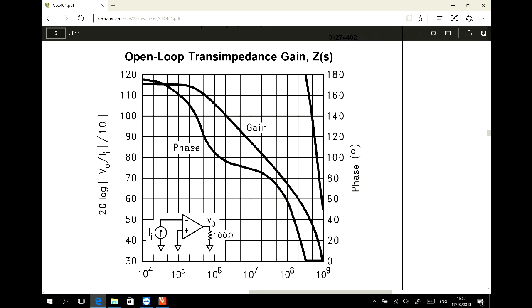In the systems, we say that we are always designing for a phase margin greater than 45 degree, because below 45 degree, it is very probable that your system becomes unstable by a very simple parasitic. So we are always trying to design our system in such a way that the phase margin is higher than 45 degree.